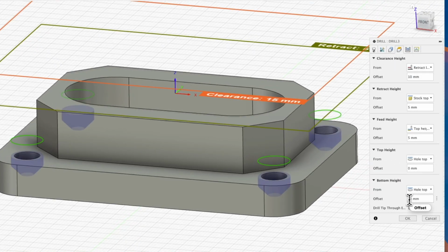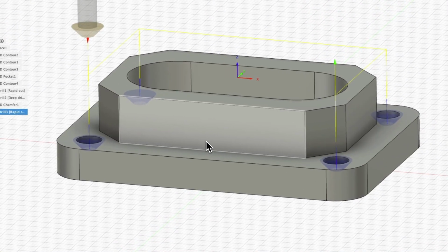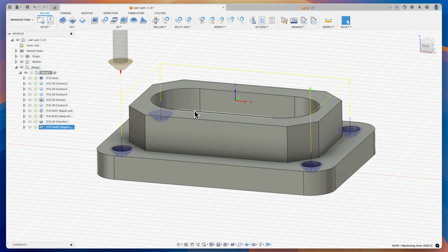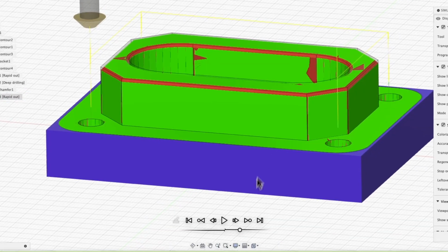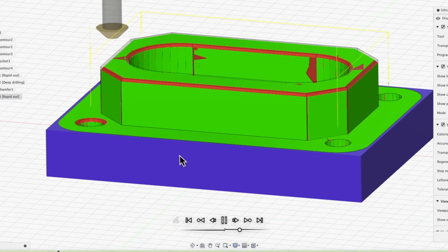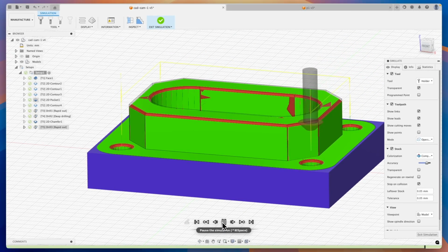I am doing this intentionally to show you that in this way you can prepare machining, and that we do not have to specify all parameters immediately during the first attempt to add a machining operation, and those parameters don't have to be perfect right away. The CAM systems give us the possibility to introduce a parameter and to see the effect of that parameter on the toolpath and on the machining. So here I am playing with that a little deliberately to show you that you can also prepare machining this way, and that we don't really have to know everything when preparing machining programs. We can simply use trial and error to reach a point where the machining we prepared will be satisfactory, correct, and can be performed on a CNC machine.